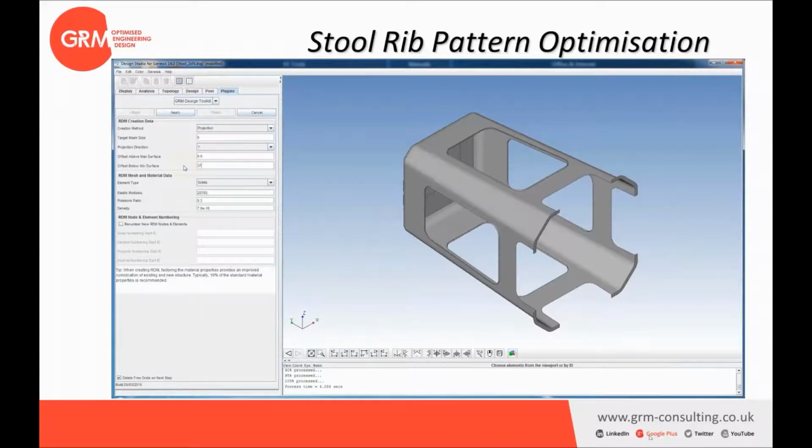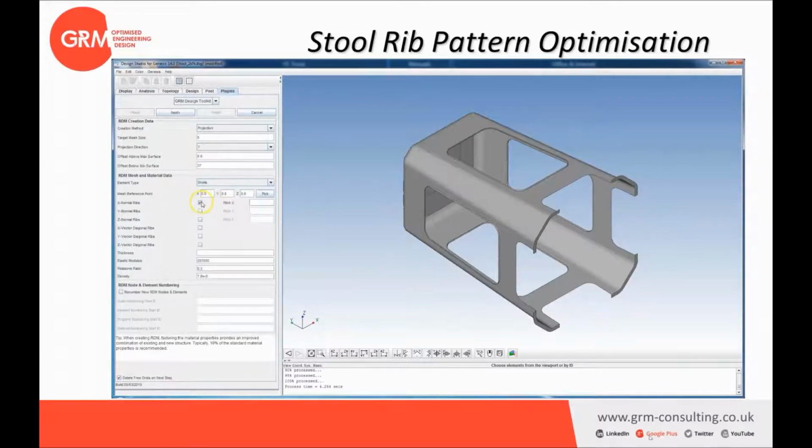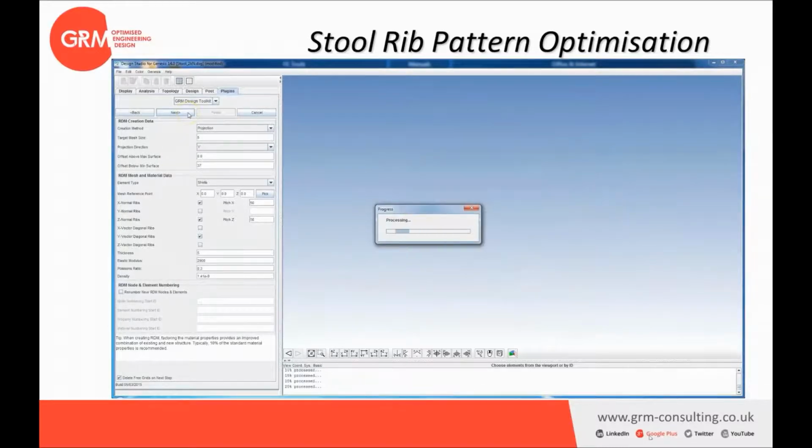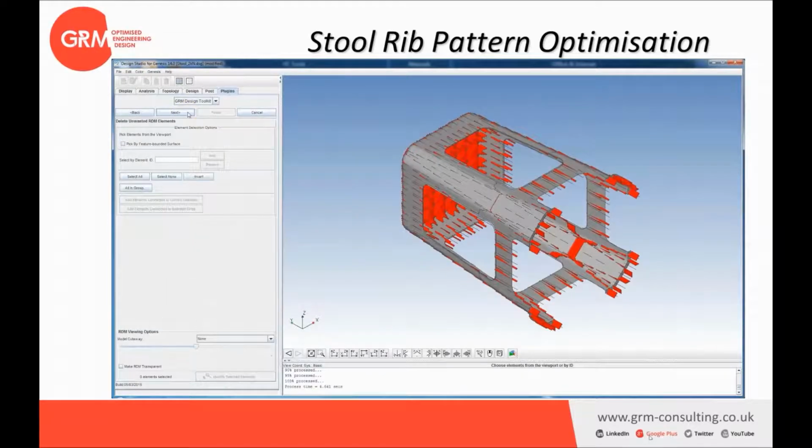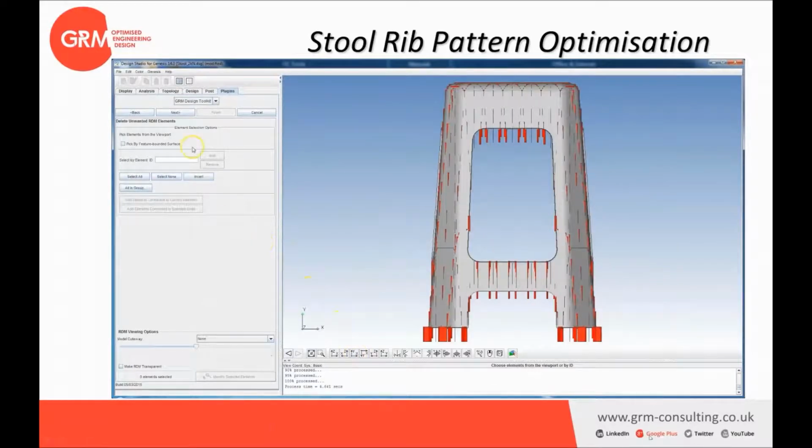And we want the ribs to be 37 millimeter long. We select the shell element type and different rib patterns that we want with the pitch that is desired. And finally, we'll define the material for the ribs, which is nylon in this case. And that's it. These new ribs have been created.